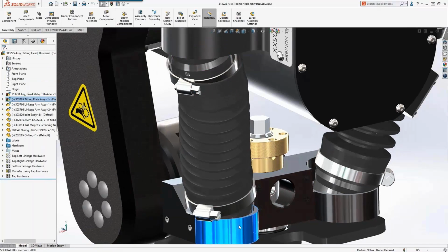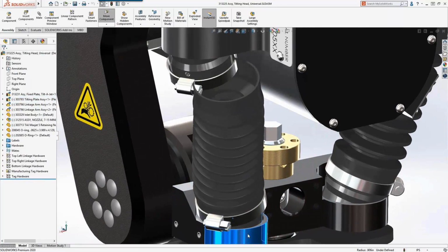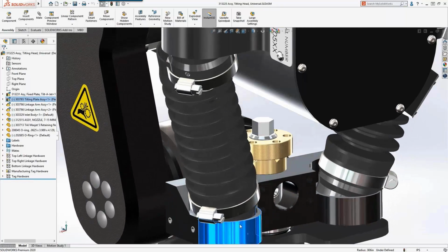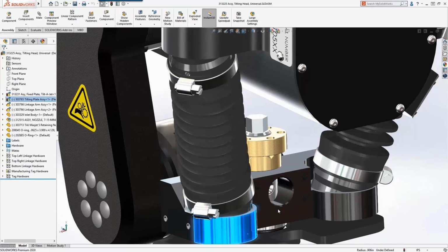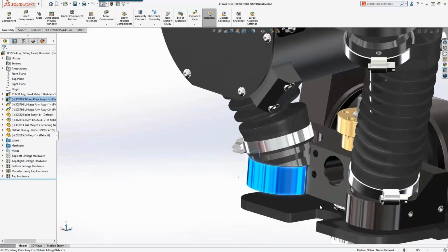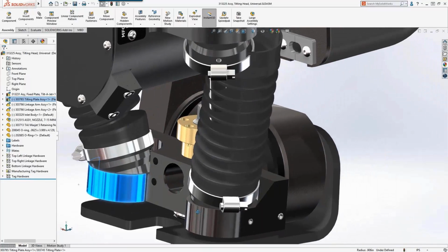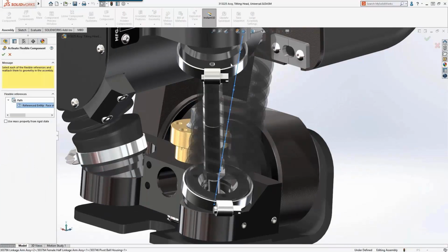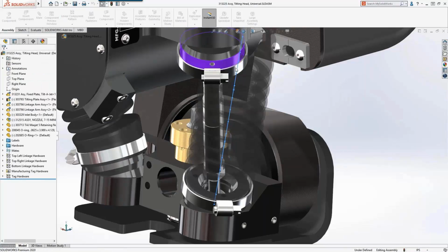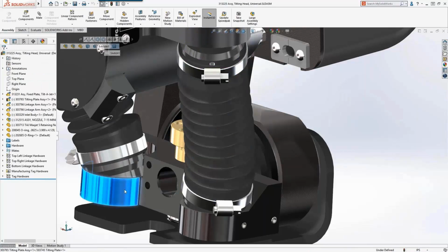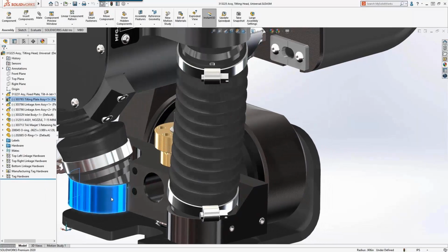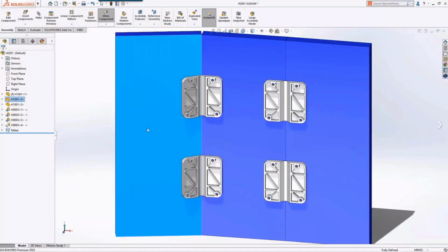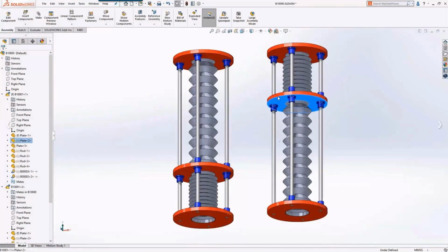In this case, the 3D path of the bellows will reference the cylindrical face of the pivoting ball housing. After clicking OK, the geometry updates and continues to update automatically after each assembly movement. This process is repeated for the other instances of the bellows part without creating unique configurations or separating part files. This optimizes your data management and efficiently brings your parts to life.